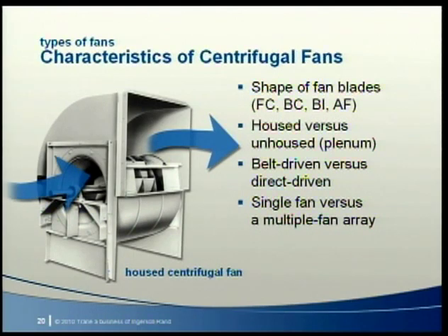A centrifugal fan may be characterized in a number of ways. The shape of the fan blades and whether the fan includes a scrolled housing are traditional ways to characterize. Other ways include whether the fan is belt or direct driven and whether single or multiple fans are used. Let's start with the shape of the fan blades.